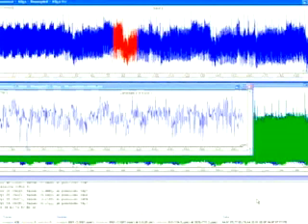The top 4 best correlating traces have been selected. You can already see that for the last S-box the top correlation is almost a half, and the second one is 0.34. So there's a clear difference between the correlations, and probably the one that's selected there is the correct one.